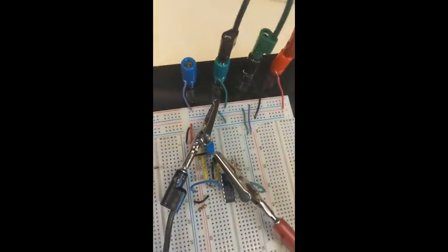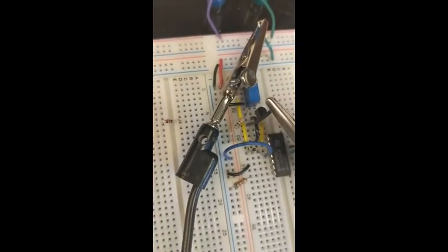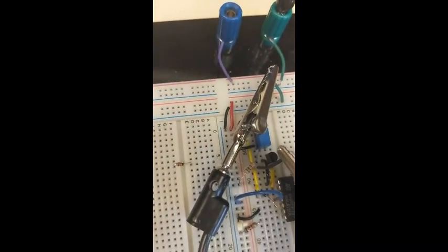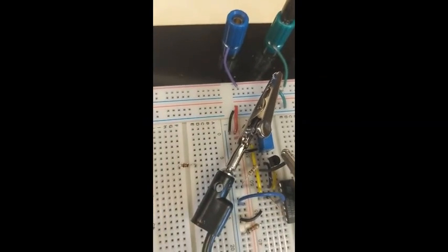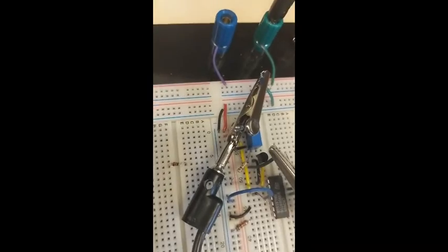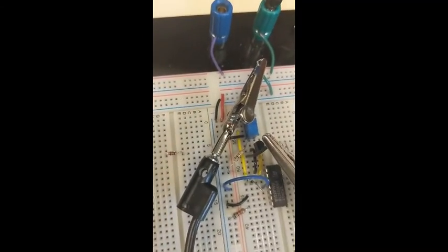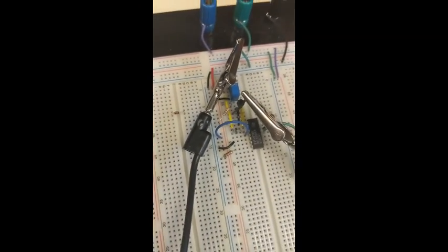Here's our circuit diagram, and here's a shot of our circuit. As you can see, we are supplying 15 volts in through the 10K potentiometer, and then we are supplying that into the positive input. And from the negative input side, on the emitter side, we have a 1 kilo ohm resistor connected to a 15 volt input, and then we use the ammeter to measure the collector current.